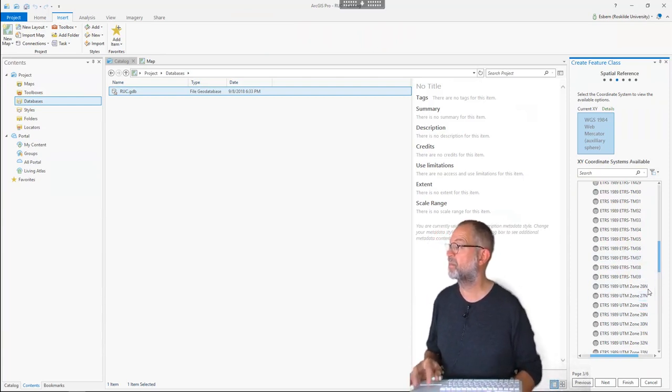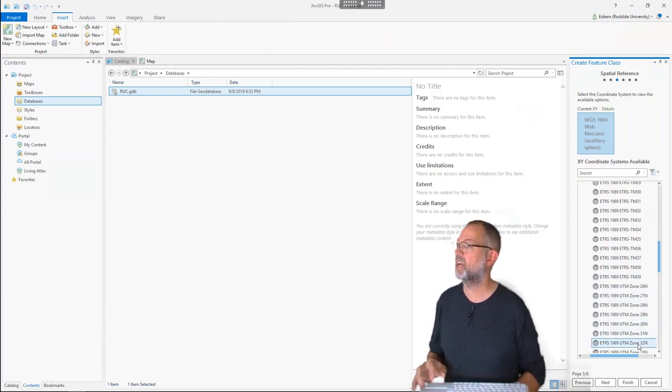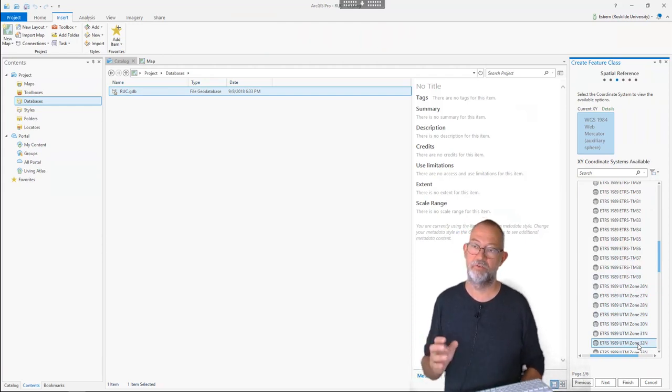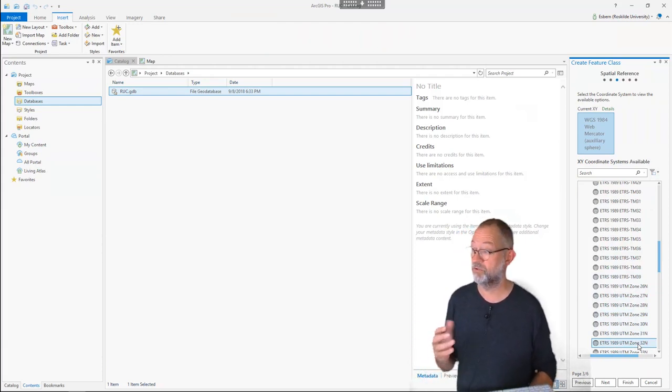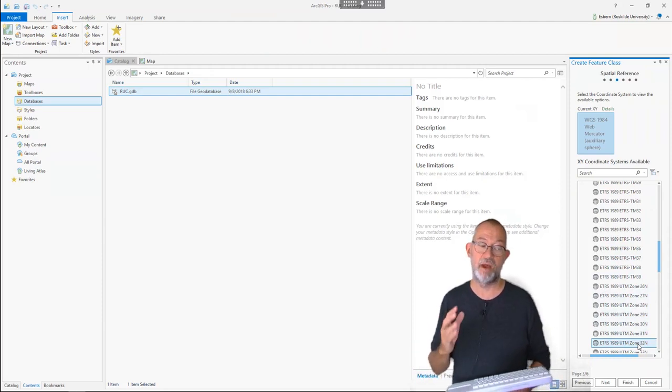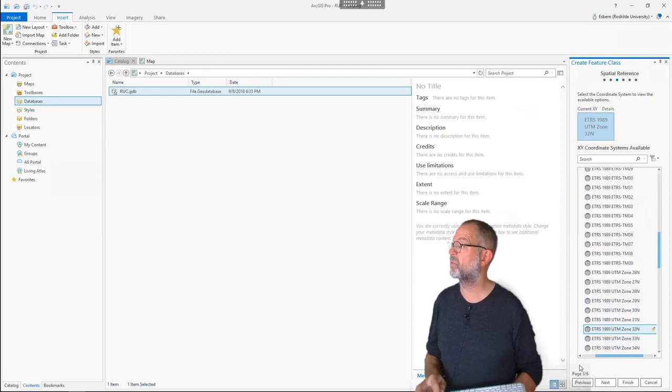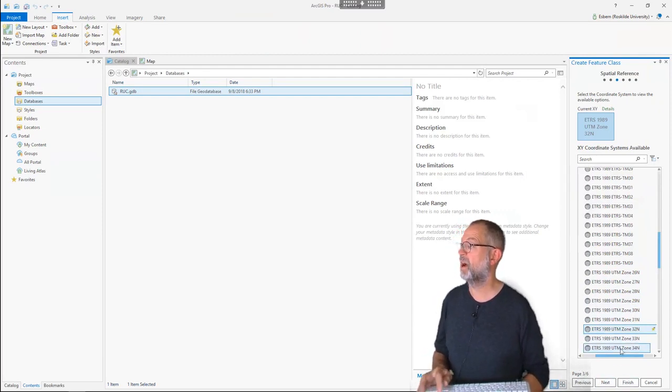And finally, Denmark is shared between UTM Zone 32 and 33, but strictly speaking, the university is in UTM Zone 32, but traditionally we do mapping of the whole of Denmark in UTM Zone 32. So I'll choose that one as the coordinate system that I'll be using. And you can see it's up here written in the blue box as the one that I'll be using.